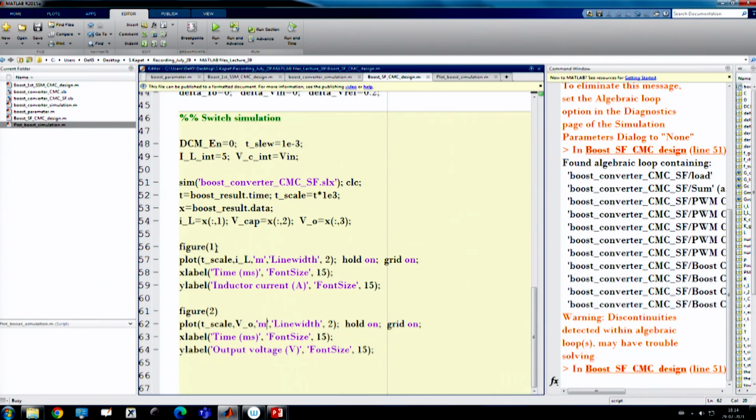Okay. So, let us wait, because we set here again 1/3, so they are the same, in both cases the crossover frequency is set to 1/3. So, I have designed by means of pole placement and then it will give the value, where in output feedback we set 1/3 of the RHP zero crossover frequency, here also we set 1/3 of the RHP zero, and let us see what happened in the response of the converter.